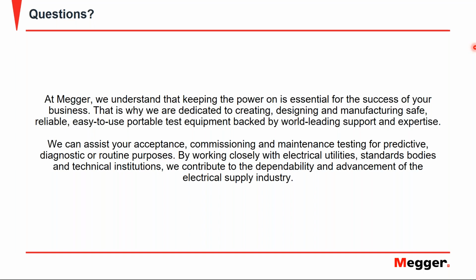So this specific example was for offline testing. Now, a typical method for online testing was electromagnetic decoupling by the high frequency CT that I had mentioned briefly. But what I was doing was an offline test, which uses the conventional method in which you're using an external high voltage supply to excite the partial discharge and take that measurement.